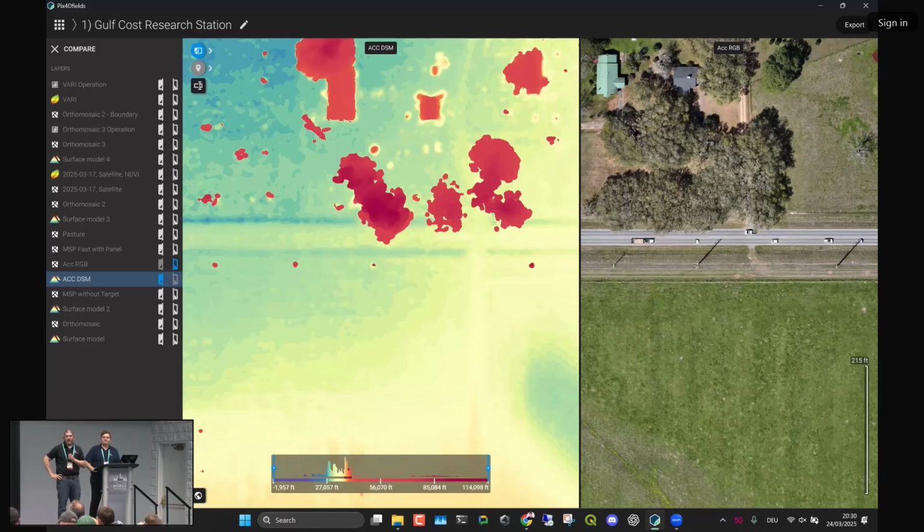Projected acres, yes. Should. But we're using UTM projections and not your state coordinates, so there might be some differences. It's going to be better than WGS 84 or something like that. That would be a very wrong way to calculate area. So that's a good question.